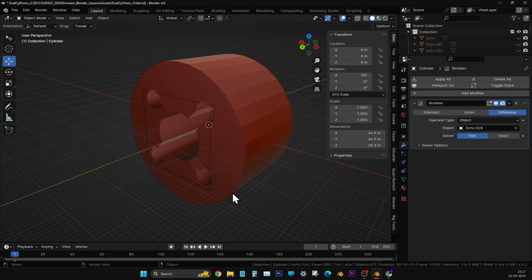Press on the sphere there, so that we can see it. Right. Now we have to remesh it. Go a little higher in the properties editor vertically. Properties panel, right side, below the outliner. Come down. That divider you can raise up. Yeah, enough.